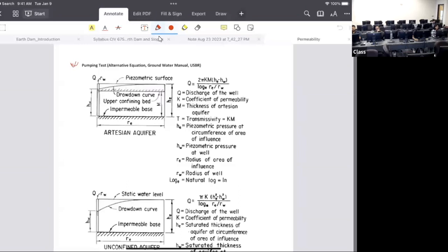And what's going to happen in the silt, or in between, with changing permeability? It will have some influence area, but there is a time lag. So for clay, you'll see no time lag. It just runs dry. You pull some water out and then it stops. You don't need to do any test. You do it for some time and you'll find out, oh wow, what happened to the water? Maybe we did something wrong.